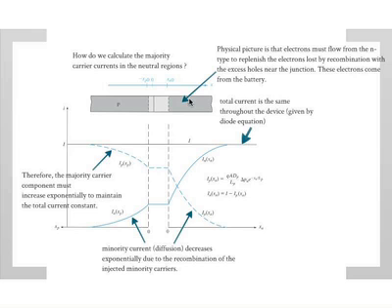Okay, so it's exactly the same thing that I mentioned for the p-type, but on the n-type, you can see because the holes are here recombining with electrons, there must be electrons coming in to compensate for that. And of course, those electrons have to come from somewhere. Outside the semiconductor, it comes from the battery. That's the current. Okay.